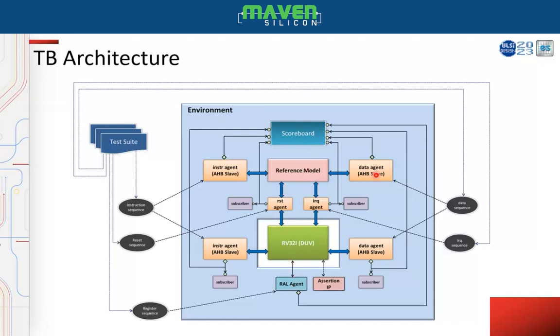Alright. And in order to make sure that we are getting complete 100% coverage, we have developed a test suite which is going to cover all the possible commands. Now let me show you the micro-architectures of various test bench components. The agents contain drivers, monitors and sequencers, and of course each agent is a configurable component.